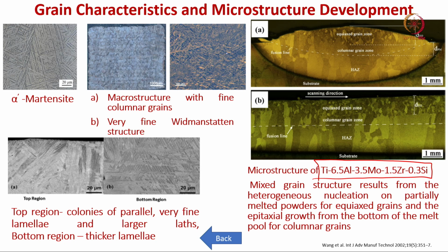Now, titanium and aluminum is the base material. So, you know it has titanium 6 aluminum, then you can add vanadium, or instead of vanadium you can add a combination of molybdenum, zirconium and silicon. Each time a small alloying element is added, that leads to the development of very different microstructures. For example, here instead of 0.3 silicon, if you add 2% or 3% of silicon, certainly you will see completely, dramatically different microstructures being generated.